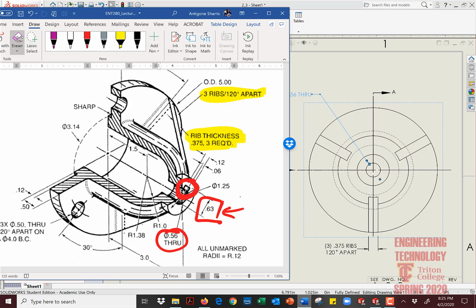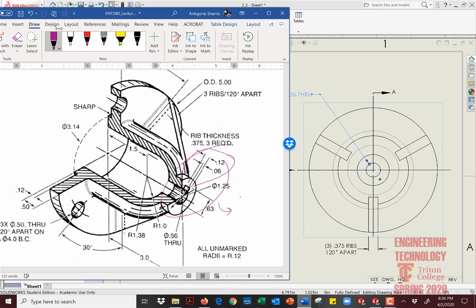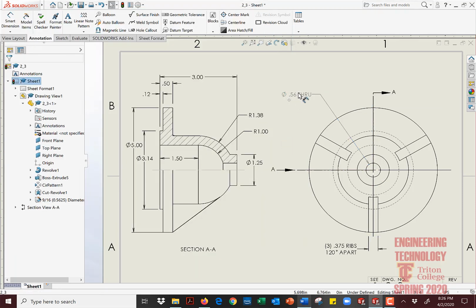And at the same time, the other thing that's being referred to here, let me clean this up a little bit, is we have this information which tells us the width of the keyway. So this entire thing, if I looked at it in view, it's a keyway that looks like this. It's in that circular spot. So the 5/8 right here actually is this, and that's what's in the drawing already. That's this dimension right here. That dimension is that element.